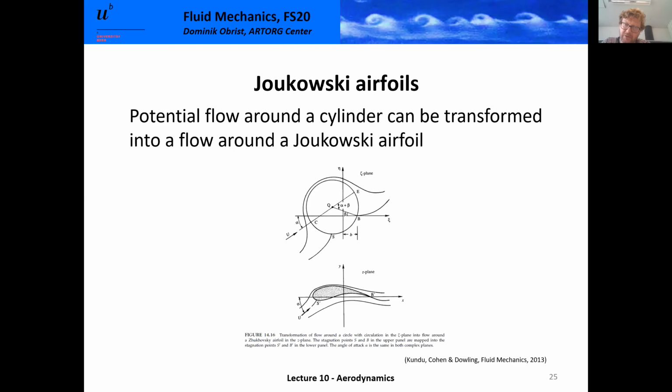In addition, what you probably should also notice, someone added a little bit of circulation to it. We're allowed to do this. This is the Magnus effect. To the parallel flow and the dipole, we can also add an ideal vortex to add some circulation. So this is the solution in the top diagram. This is something we have done 3 or 4 weeks ago. If you take this complex potential, you can just write it down. You have the tables, you just write it down. It's one line.